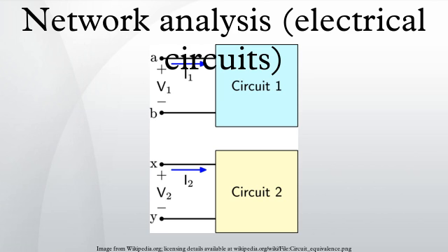These could be the forward transfer function, the input impedance, the reverse transfer function and the output impedance. There are many others. One of these expresses all four parameters as impedances. It is usual to express the four parameters as a matrix. The matrix may be abbreviated to a representative element. These concepts are capable of being extended to networks of more than two ports.